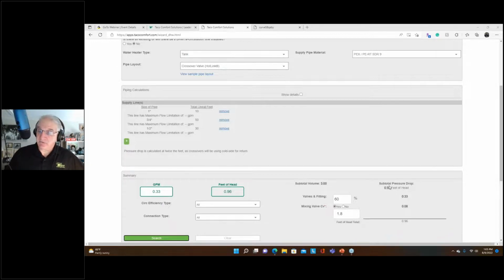Do we deadhead the pump then at that point? That's another question people have. Do we deadhead the pump? Sure do. Yep, we sure do. We do deadhead the pump for however long. If we're on that 5-minute on, 10-minute off cycle, are we deadheading the pump? Absolutely. Is it bad? Not at all. The pump is running at a minimal speed anyway, number one.